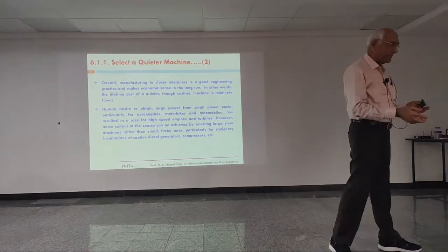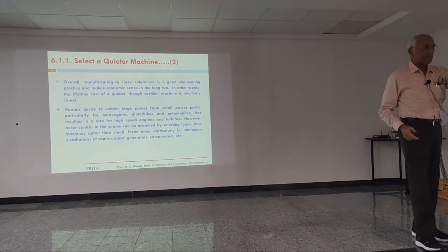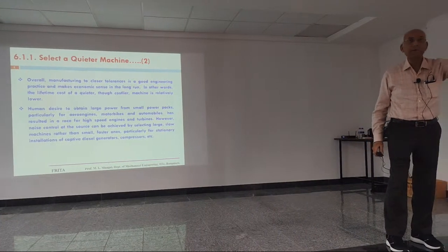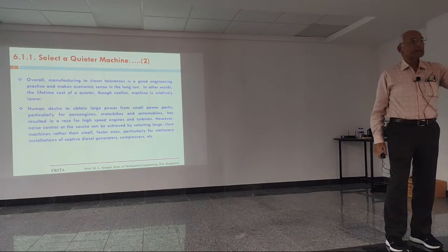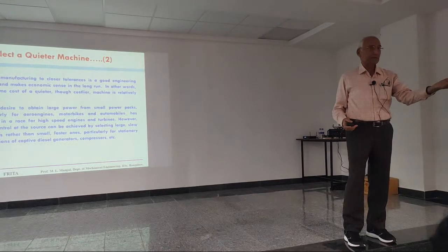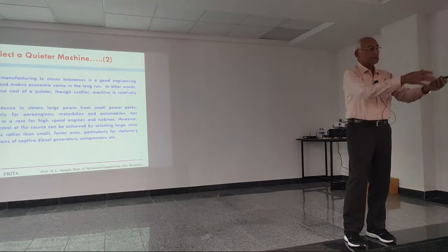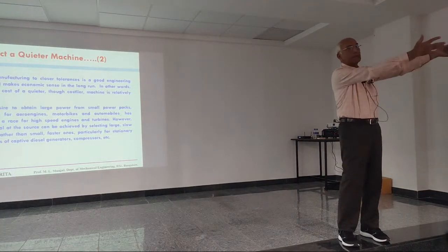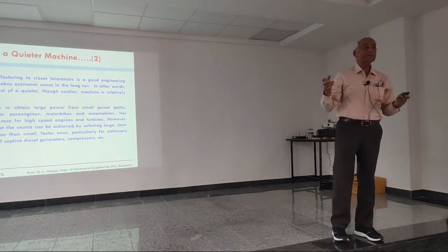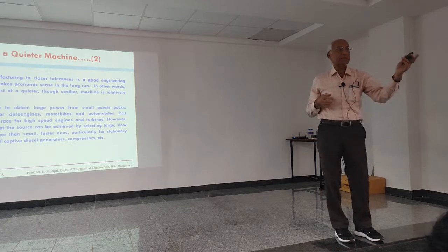If, for example, instead of the size of, let's say, half the table, the compressor is double the size of that table, all I am spending is maybe 10% extra on the steel cost, material cost. And ground, this doesn't matter wherever the compressor is lying. The space cannot be such a problem at all. So unnecessarily, why should I design that compressor to run at higher speed?